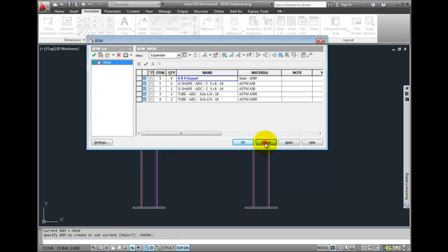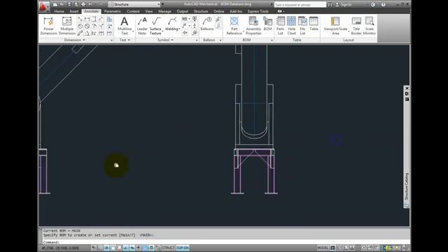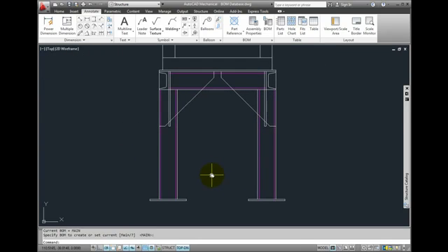Part references can also be added at the assembly level. If I scroll over to the right side view, there I have geometry that is going to be representing a side gusset. I can add a part reference right here and then later pick that up when I create the block from this geometry.